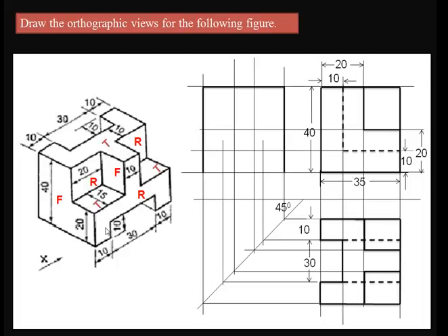Now I would like to draw this edge, wherever I am showing my cursor here, which is equal to the length of 10. So we need to draw 10 here, and similarly draw another edge which is again at a height of 10, so already represented here as the 10 line. Now join this until it intersects this construction line, which means this edge point to this edge point will be shown.